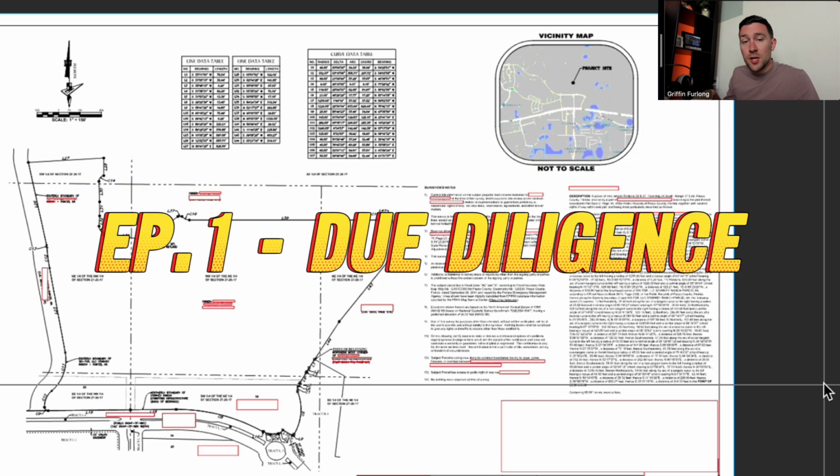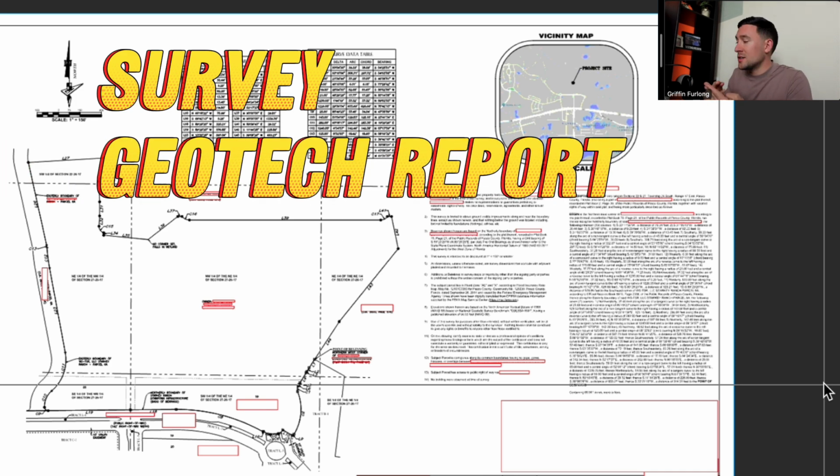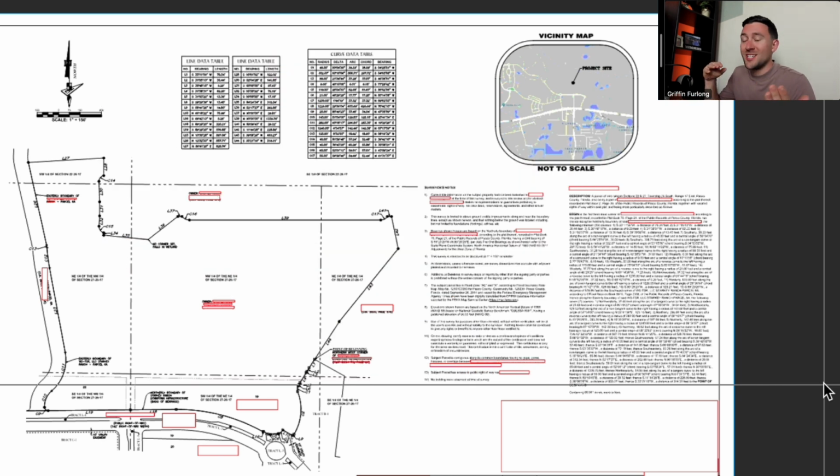But in today's video, we are going to dive into the due diligence effort of a land development engineer. And what we're going to do is review the documents that we typically receive from other consultants. This includes a survey, topographic survey, geotech report, traffic study, and a Phase 1 ESA, which is really just an environmental report. We're going to walk through each type of document we receive, why it's important, and what I typically review when I receive those materials.